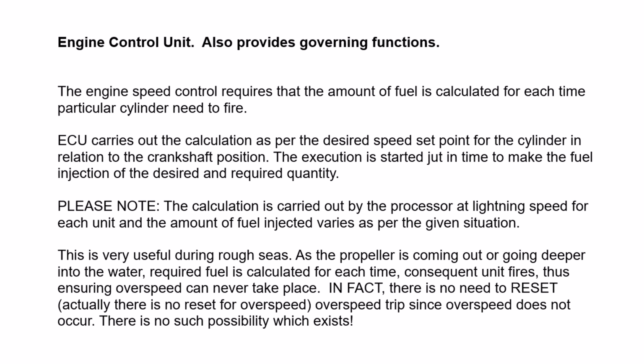That's the beauty of a computerized processing unit. The ECU carries out the calculation as per the desired speed set point for the cylinder in relation to the crankshaft position. The execution is started just in time to make the fuel injection of the required quantity.